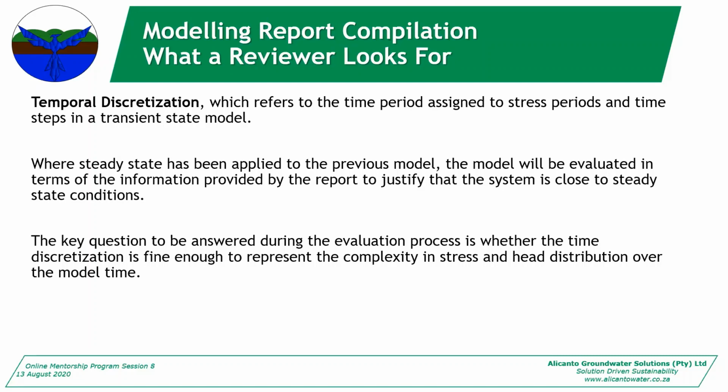Yeah, definitely. I think I know what you're talking about. Look, in terms of the stress periods, in terms of the recharge, that would be your time steps. So then you would have a wet season stress period and a dry season stress period, where you vary your input to the system in terms of your recharge. Okay, so that's your temporal.